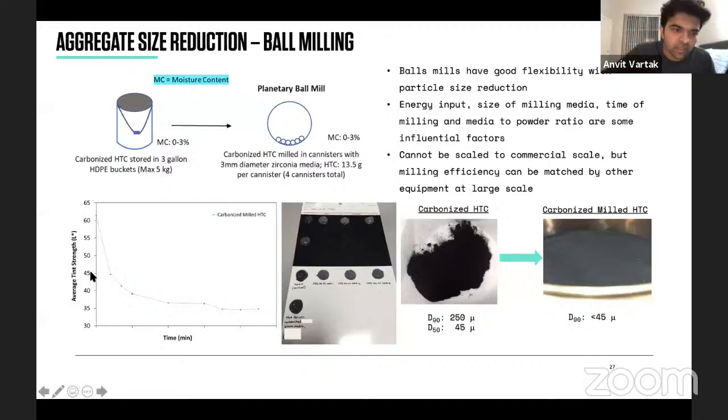So a lower and lower value means better, smaller and smaller particle size and darker paste. So it gives you a good evaluation of what you're doing with your ball milling parameters and whether you are getting there or not. So the target is roughly 35, and with higher and higher milling times, you reach that target,